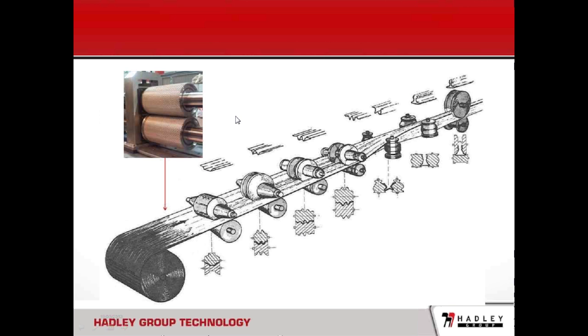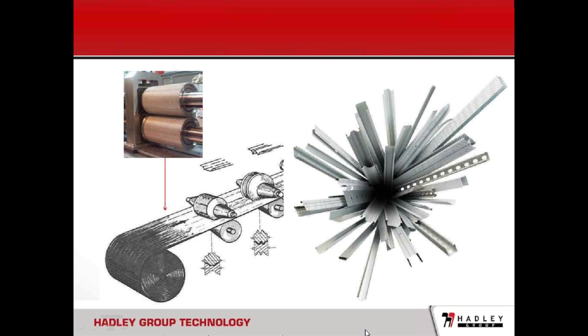The dimpling process is a process that is applied prior to the traditional cold form process. In this dimpling process, we use a pair of two rolls with a special desired pitch, so that we can stretch the flat strip to apply the dimple above or below the strip to develop it into the dimple strip. Then the dimple strip travels through the rolls of the traditional cold form process, and then we can develop a variety of dimple products that we show on the right side here.